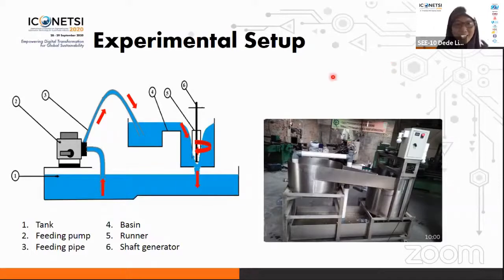Thank you. And then the water hits the runner, and then the electric power was measured by a dual module DSN-VC 288. It is put inside the electric panel equipped by 2 LED lamps here, and a stopwatch and measuring bucket were used to measure the water flow manually.